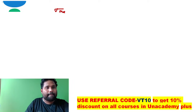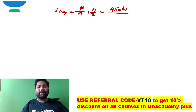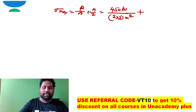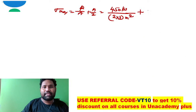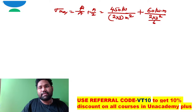Sigma max is P by A plus M by Z. P is how much, brother? 450 kilonewton. It is acting on what area? It is acting on an area of 2 meter by 3 meter, so 2 by 3 square meter, plus the moment. The moment that was provided is 60 kilonewton meter. So I can write 60 kilonewton meter by Z. Z is BD square by 6, so B is 2, BD square by 6.